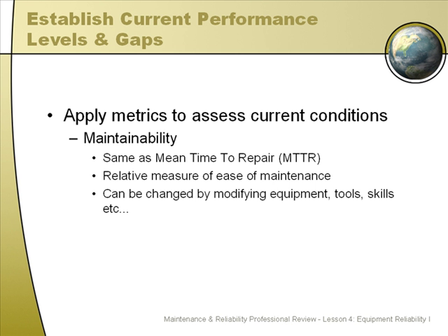Let's talk a little bit about maintainability. As I mentioned a few slides back, maintainability is the same measure as mean time to repair. It's just a relative measure of the ease of maintaining a piece of equipment. If the mean time to repair a certain type of pump in your facility is 2 hours, and another pump that does the same kind of work can be repaired in a mean time of 1 hour, you have a definite advantage to use that second pump. That second style of pump is cutting half of the maintenance time off.